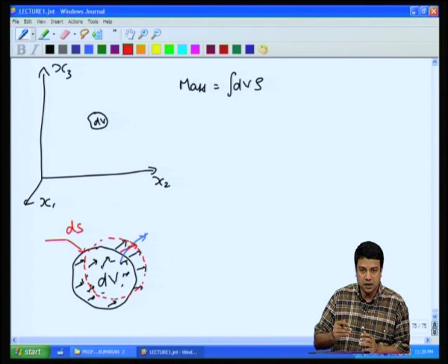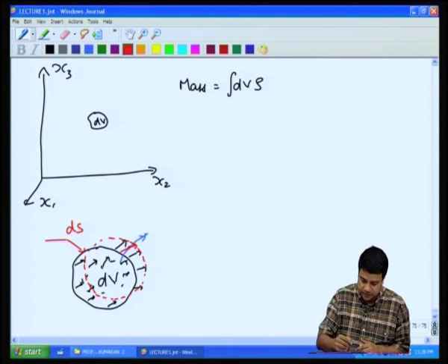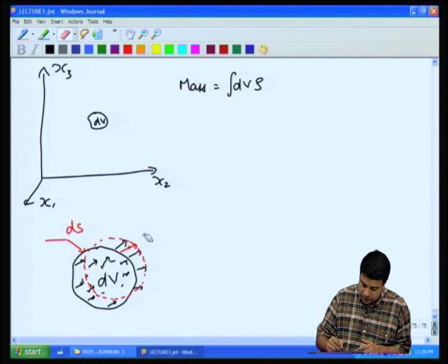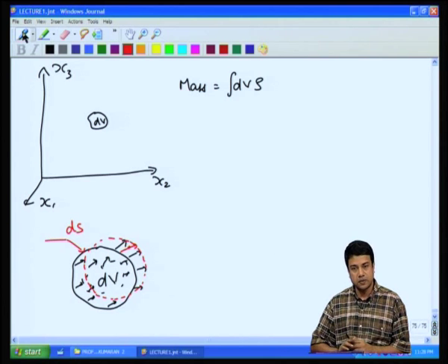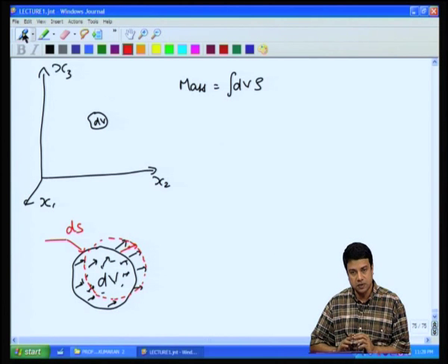If it has to cross, it will be a double valued function, which it is not. It is a single valued function at each point in space. Therefore, one cannot have the crossing of trajectories. What is outside, what is inside, and what is on the surface continues to be on the surface, provided it is a material point which is moving with the same velocity as the fluid velocity on that surface.